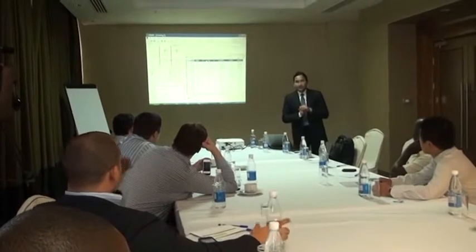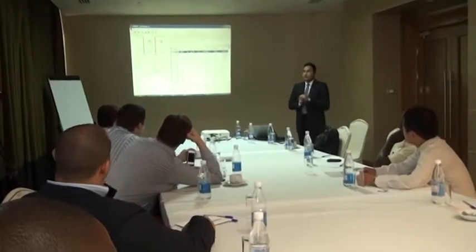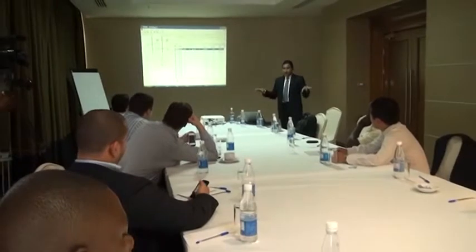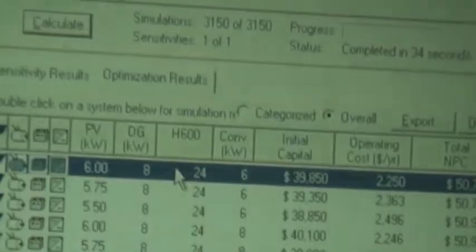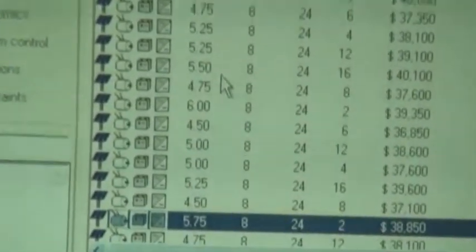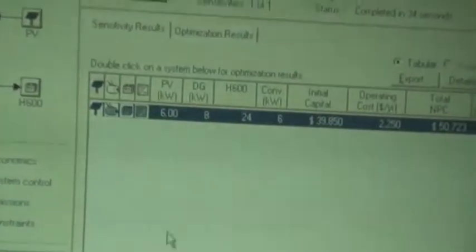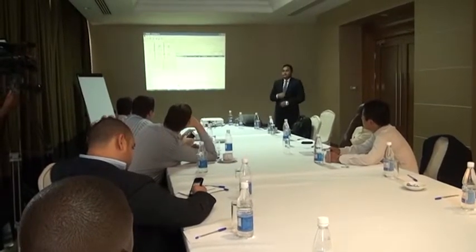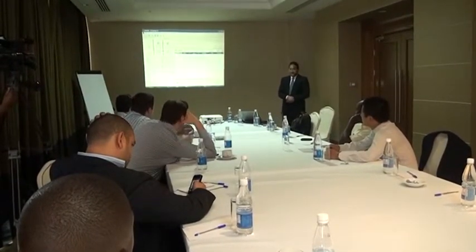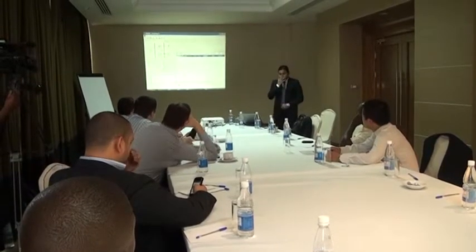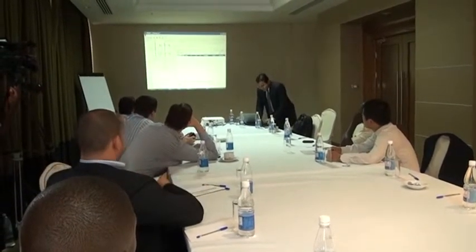If you think this is not possible and you can only go up to 4 kilowatt, so 4 sets of PV installation, then you have to look at the options for 4 kilowatt, and even in 4 kilowatt there are multiple options given. Today, we'll only look at 6 kilowatt, which has been suggested by HOMER. If you are aware of your land limitation, can you limit the PV panel size during the initial phases? You can't do that, yes.